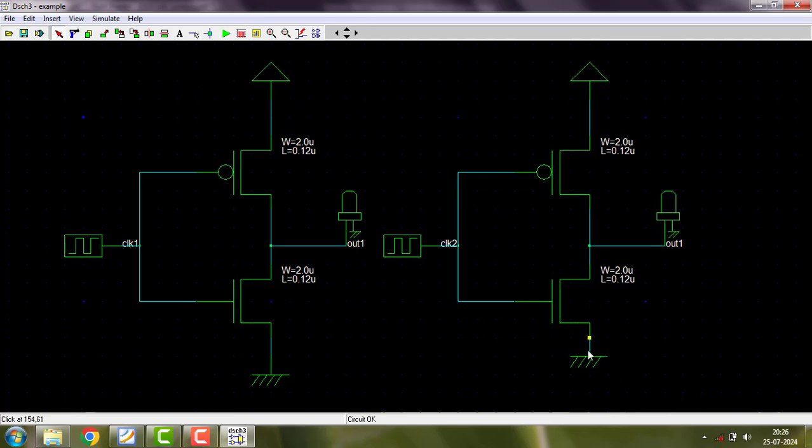I feel there's a doubt here, so I can use this icon, view electrical net. So this is not connected to 0, this is 0.3, so I should be careful about it. Then I have to take a wire and connect. Always place it with a distance and connect it with wire. That would be good. Now this is 0 and 0.